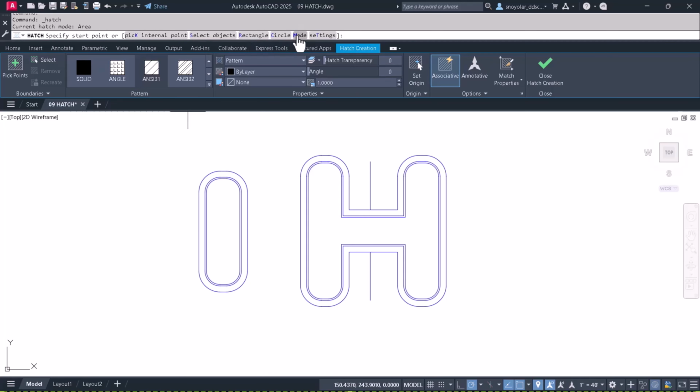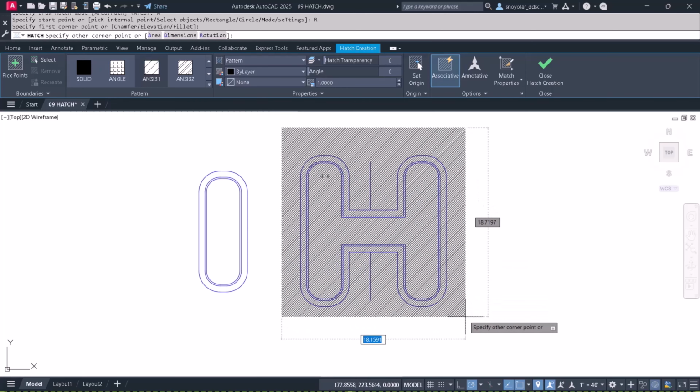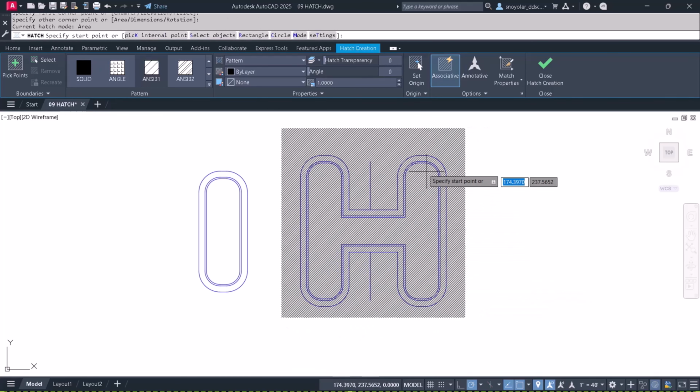When selecting the mode, we are given two options, namely generating areas or following a path from which we can choose. If we move towards the area, you will see that we have rectangles here. Let's select a rectangle. I will indicate a point on the screen. We draw the next corner and our hatch is generated. If we switch modes and now indicate that it should follow a path, the software will automatically create the desired pattern along the specified trajectory.